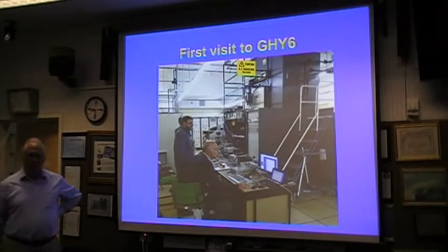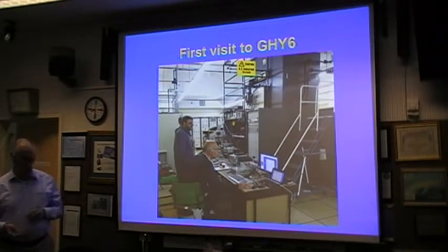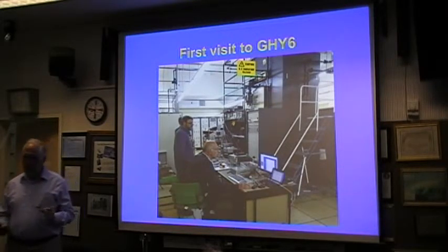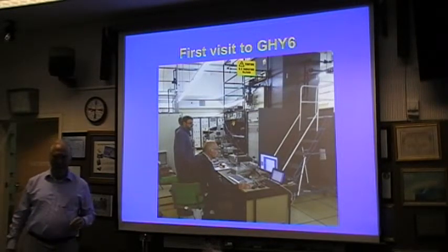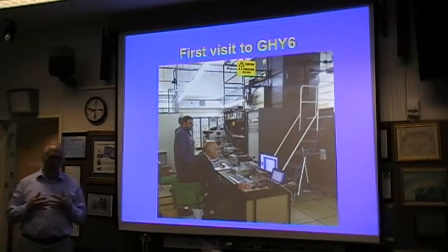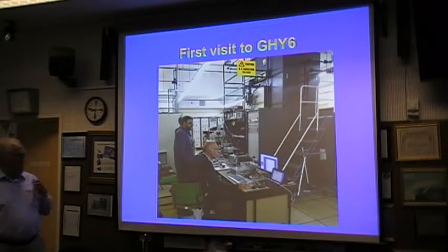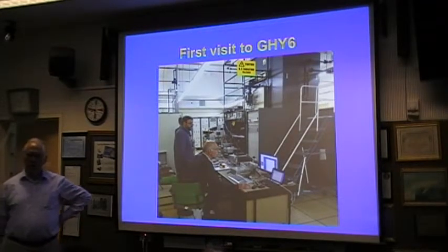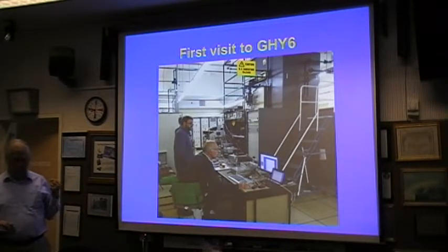It was all a bit heavy going because of the descriptions I was getting at this stage. They had called me in because I'm an EME person and do radio astronomy, and I was saying, give us a clue, what is the interface to the antenna? Is it some sort of rectangular pipe type thing, waveguide? And if so, would you mind telling me what size it is so I could have some idea? I got fairly vague answers to all this, and it gets worse. But we got there and found it was, what was it, WG11A or something. It was one size on one side, and I forget the other side, but it was fine for 5.7 gigs.